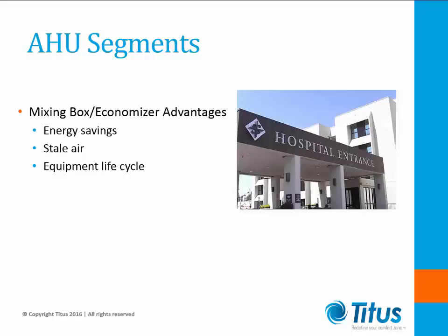In healthcare facilities, economizers are great energy-saving options due to 24/7 facility operation. So when running at night, economizers can serve the building by using cool night air. Using increased outside air should encourage a healthier environment for patients by reducing the use of recirculated stale air and reduce runtime of compressors, pumps, chillers, and condenser fans on refrigerated units. Economizers can extend the life of your HVAC system and components.